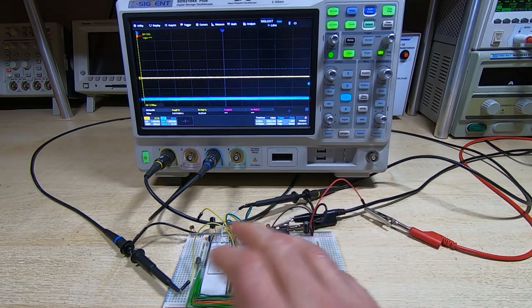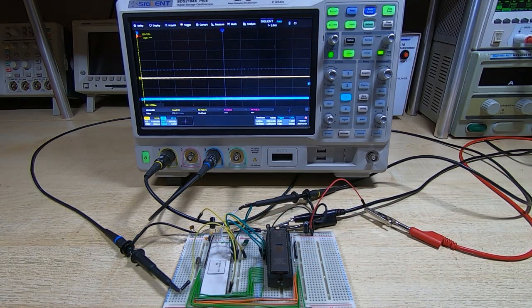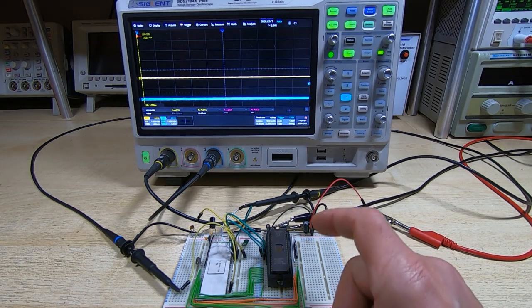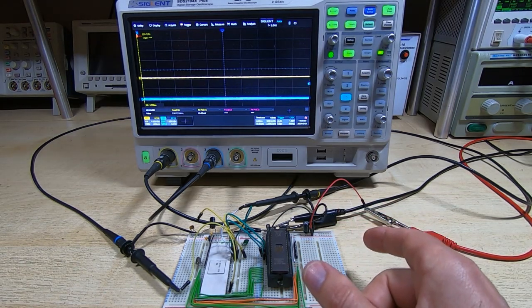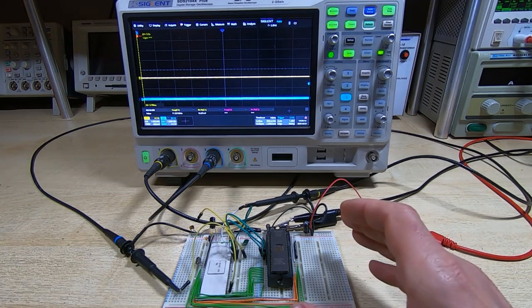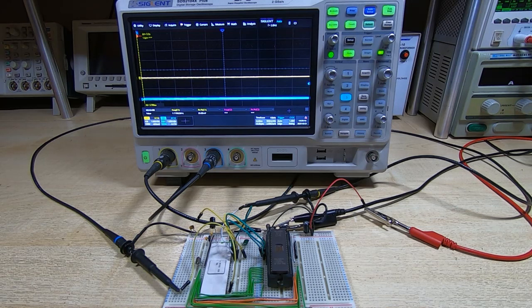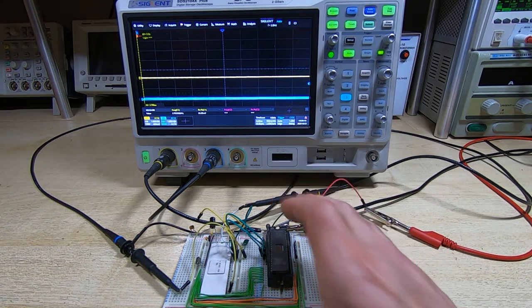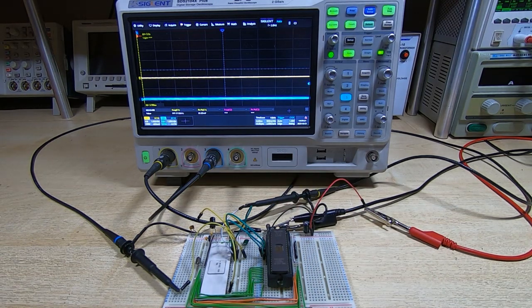And the reason I chose this is, firstly, it's a very interesting processor, but also it gives us access to effectively the inner workings of a microcontroller that we wouldn't normally have access to. You don't normally have access to the internal buses, you only have access to the external ports, but with a setup like this we can gain direct access to those internal signals, and it makes it easier to explain how it works, but also will be far more interesting in using the logic analyzer.